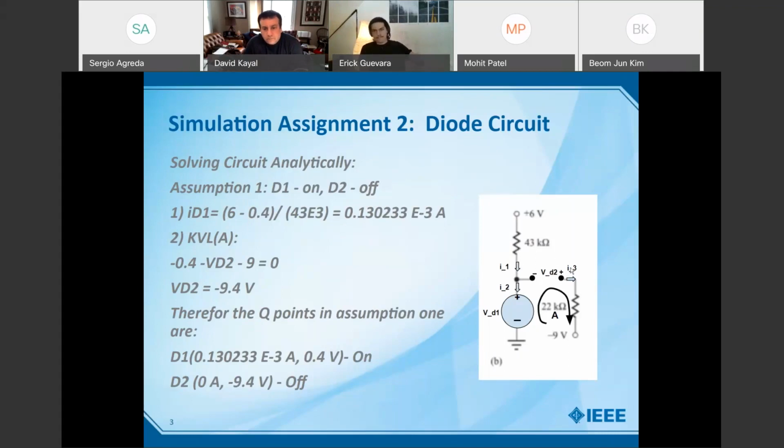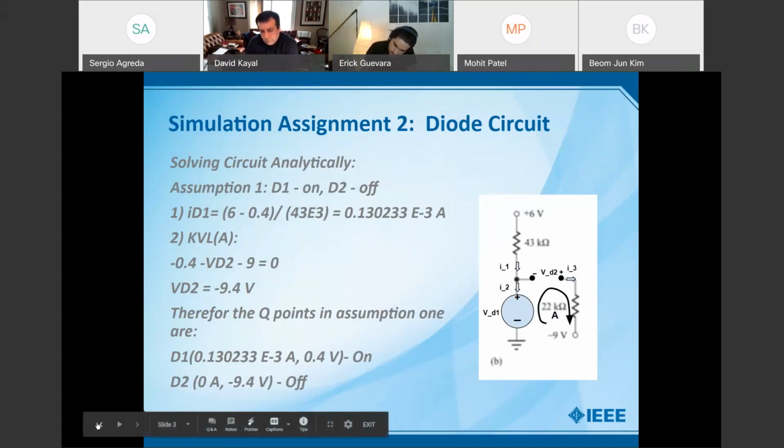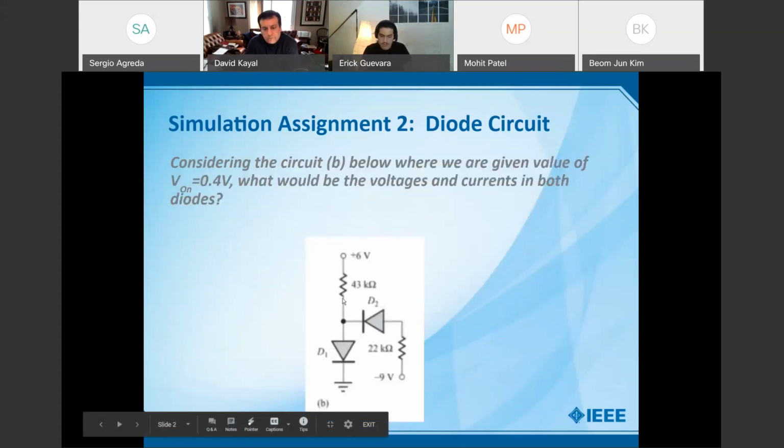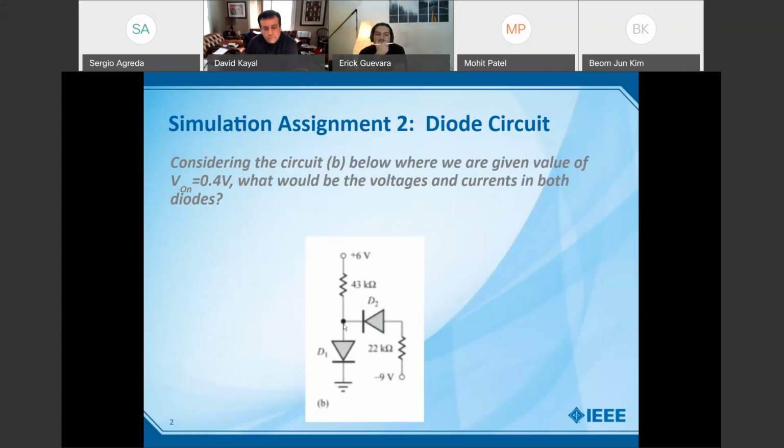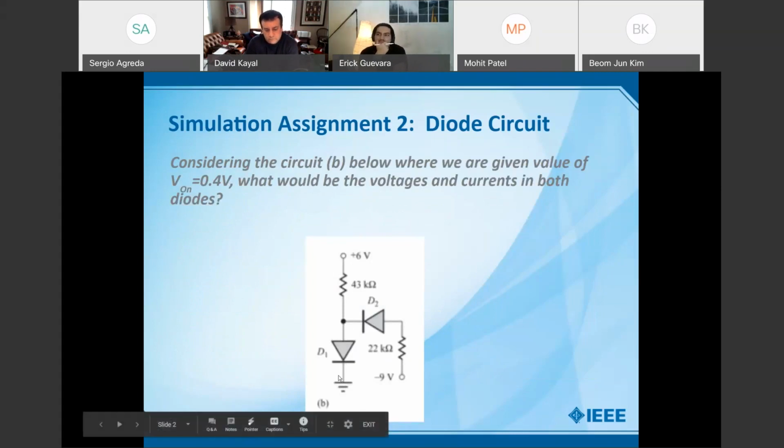So I3 is always 0 when it's open, because open circuits have no current running through them. That tells us, at least in this assumption, I1 is equal to I2, and that means there is current going through this diode, which is in this configuration and allows a voltage drop to be active here, and current running from top to bottom of that branch.